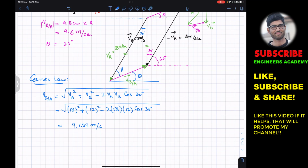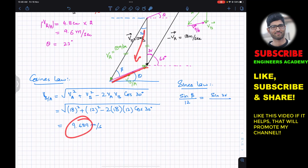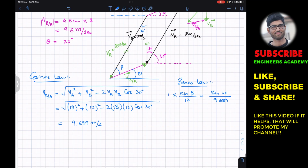So if I apply sines law, we can write that sine of beta divided by the magnitude of the opposite side, which is 12, equals sine of 30 divided by the magnitude of the opposite side. The opposite side is this VBA, which is 9.689. If you multiply both sides of the equation by 12, 12 will cancel out.